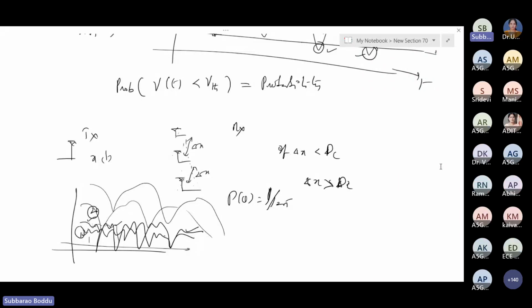That's why there is a limit to the number of antennas. So your query is how, at the component level, this is related to the diversity gain. Yeah, and the maximum value of the diversity gain we expect is up to 10 dB, right, sir? Yeah, these are the numbers, but considering how many antennas, for what antennas and what frequency, you have to decide the spacing. They all matter.